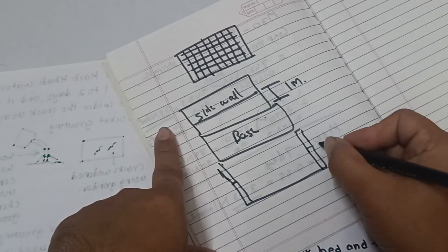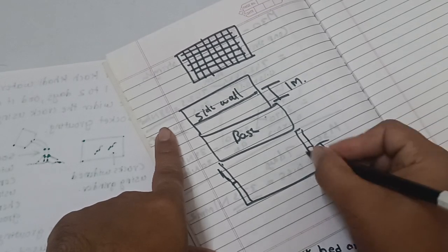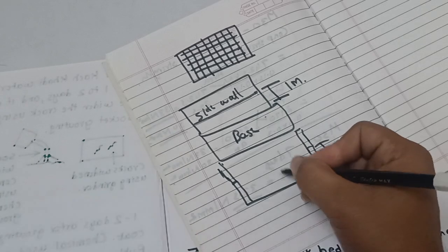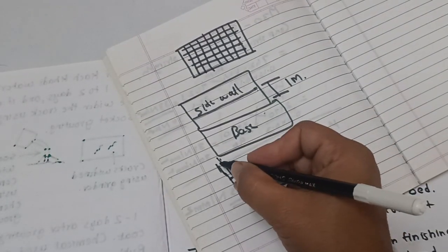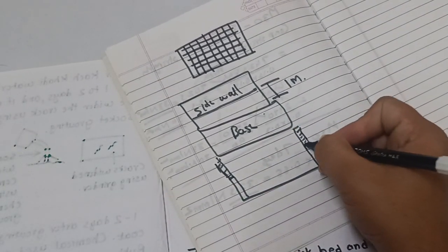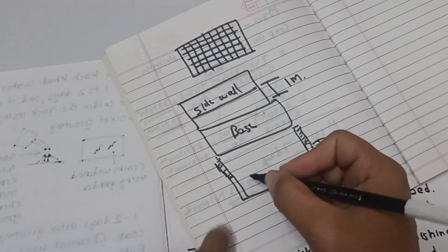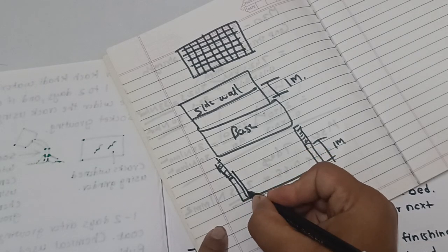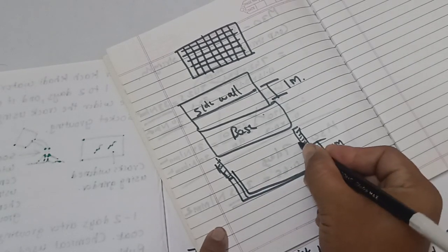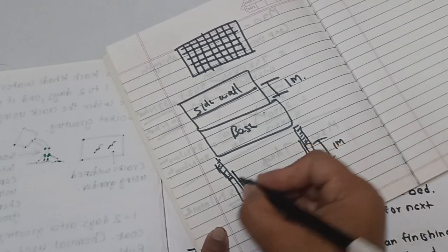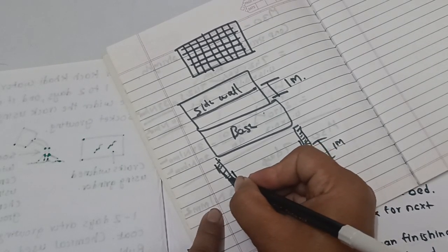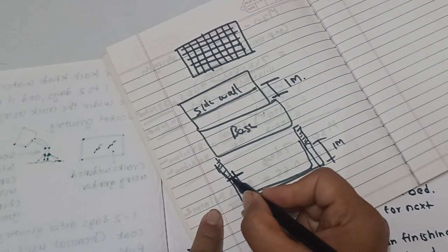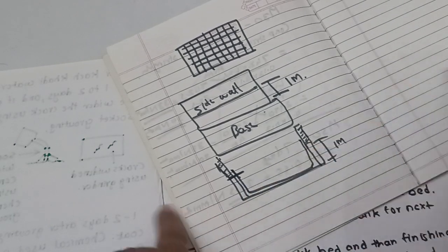is not plastered. Like this portion is not plastered, because we do waterproofing here. So for example, this is plastered. When we apply the chemical coat, we should overlap this by 50 mm. This way we should do waterproofing. By doing this the joint is sealed. This is a point where leakage can happen, so this is sealed properly.